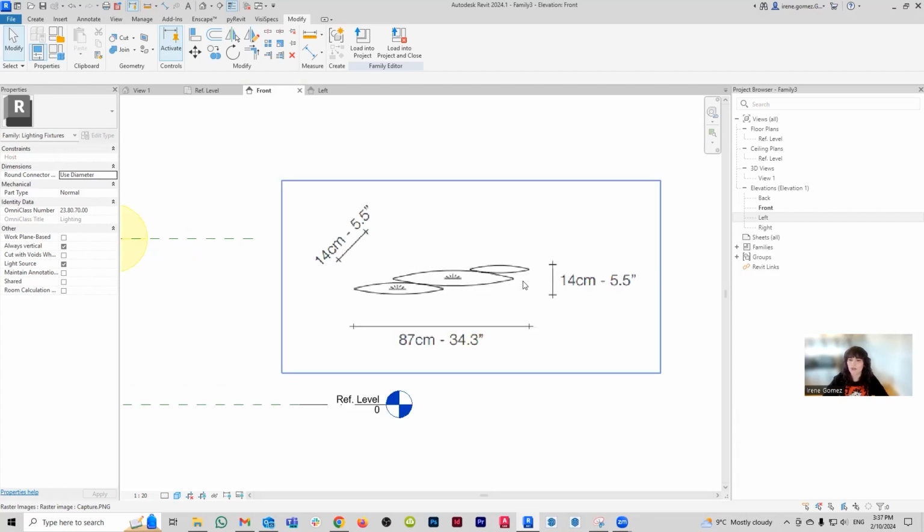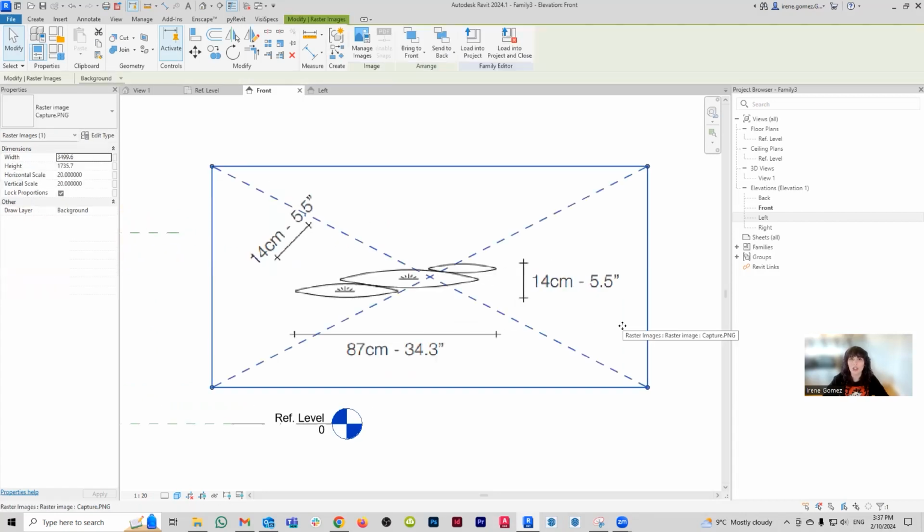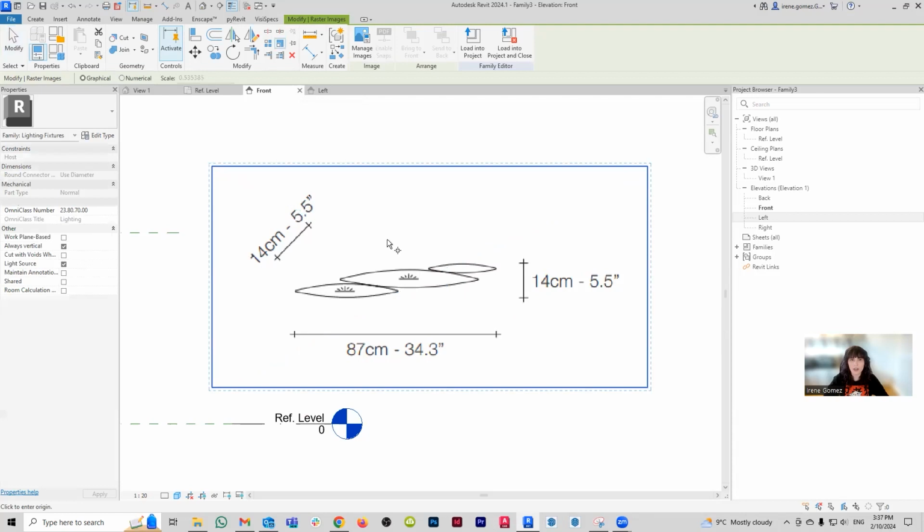To scale images in Revit, all you need to do is select the image, and you're going to use the scale tool, which is this button here, or quick key RE for resize, RE. Now, when scaling images in Revit, you're going to have two options, graphical and numerical. Numerical is basically order of magnitude. So you're making something 2 times bigger, half the size, and so forth. Graphical means that you're going to pick 2 points within the boundaries of that image, and then you're going to tell Revit what the distance between those 2 points should be.